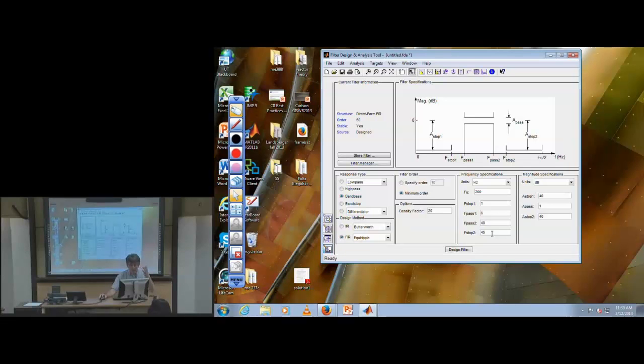And the last thing is that the transition band is about 10% of the bandwidth of the filter. That's a rule of thumb that we'll see play out many times. So the bandwidth here is 34 hertz. 10% of that's 3.4. So you could go as low as like 40 and 43, or do 40 and 42 or something. I just want to give you something that gave you reasonable filters to work with. All right, so let's design this.